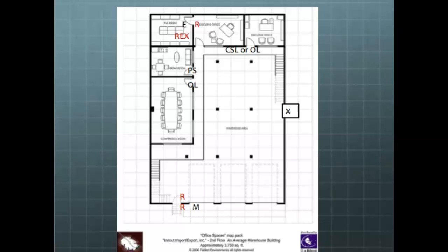But I think that's a place where you have a reader in, because you need to know who went in and when. And then a REX to get out, because the instructions basically told you didn't need to know when they went out, just who went in the room. I used an electric strike on that one because there was no chance of any weather interfering with it. And then also with electric strike, you can use a crash bar on the inside or some override so people can get out easily.